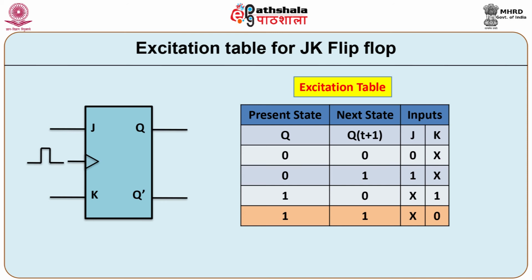The JK flip flops are normally preferred for almost all designs because the excitation table indicates do not care input either at J or K inputs for all present to next state transitions. This helps in eliminating many terms from the next state equations.